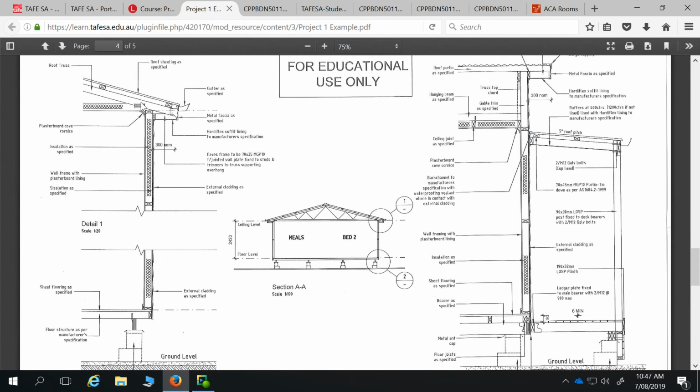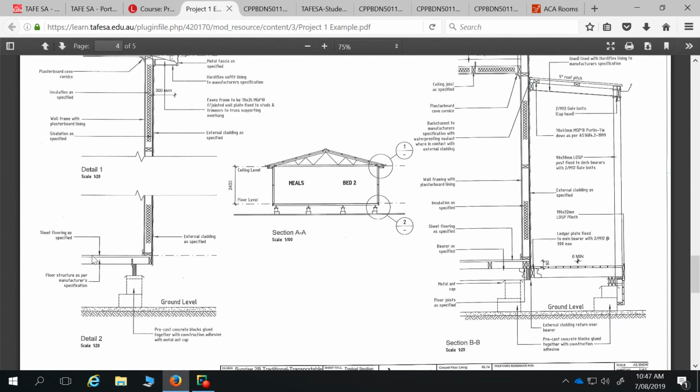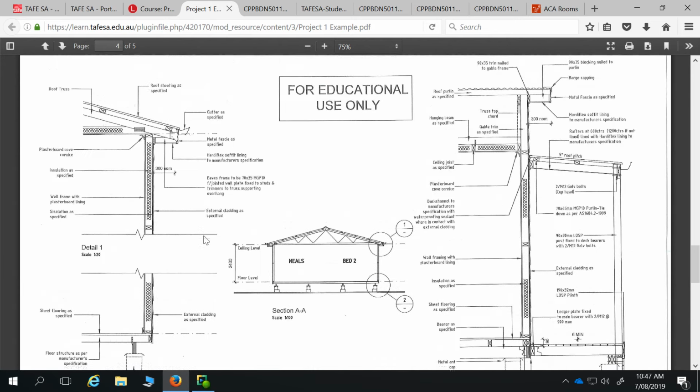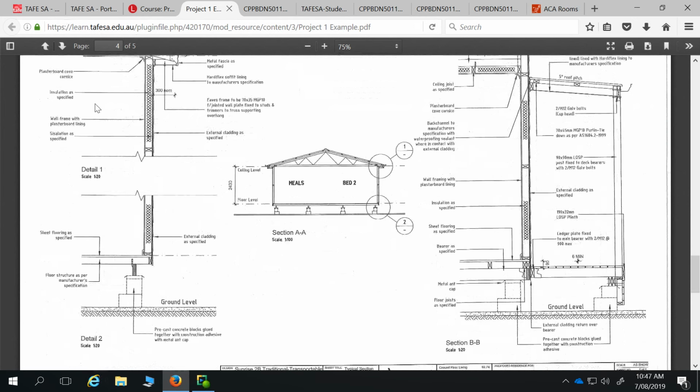So we'll just show how that truss, and we will show the bottom and top chord in a bit more detail with the nail plate, etc., sitting on top of the top plate, coming down to how it's sitting on the blocks on the ground. So we will use this as a full detail 1 and 2 when we do it, and this one at 1:50.